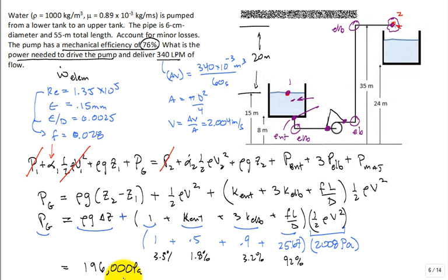If the pump can't have a pressure of at least that, it won't even be able to push it up the pipe. If the pump only puts out 196 kilopascal, it'll just be able to fill the pipe and hold it there and not really spit it out. But it's going to have to spit it out or have a higher pressure because it has to overcome the friction, etc.